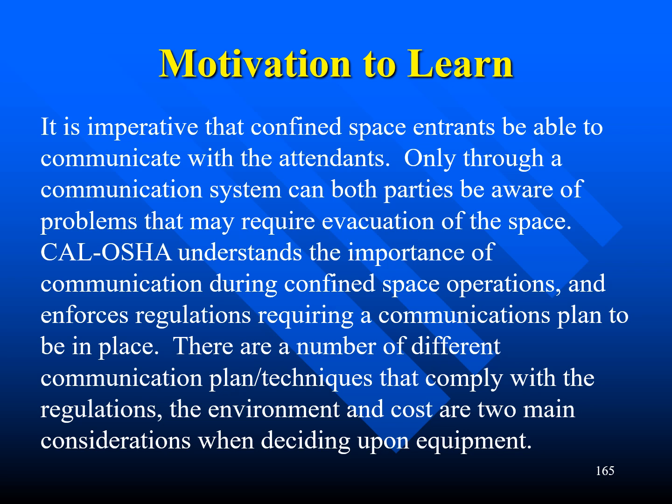It is imperative that confined space entrants be able to communicate with the attendants. Only through a communication system can both parties be aware of problems that may require evacuation of the space. Cal OSHA understands the importance of communication during confined space operations and enforces regulations requiring a communications plan to be in place. There are a number of different communication plans and techniques that comply with the regulations. The environment and cost are 2 main considerations when deciding upon equipment.